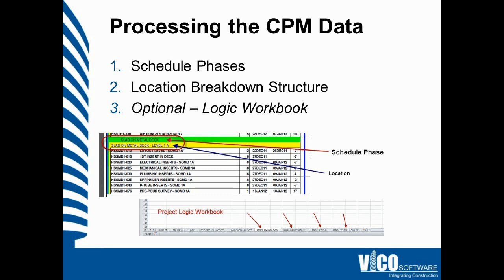Typically, that information is identified in, let's say, a Primavera schedule as the headers, as you can see indicated in the images on this screenshot. Now, as part of our own internal process, we usually take this information and start to dissect it from the CPM schedule and plug it back into a spreadsheet that lays everything out nice and neat for us to copy and paste basically back into the Schedule Planner format.